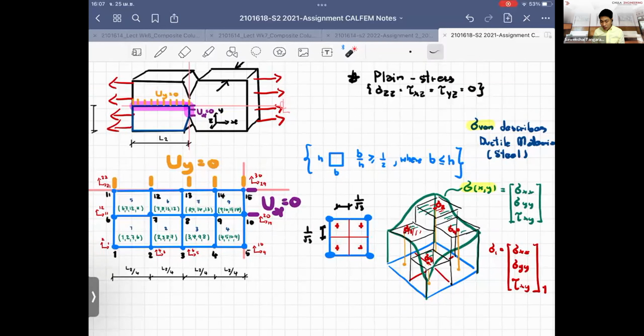We use the concept of the Gauss point, which means we try to approximate the hyperplane, which is nonlinear, by using a constant plane of the linear within the element. So the more Gauss points, the more elements, and of course, when you increase the number of Gauss points, you have to increase the order of the displacement function and so on, the more accuracy you have here.